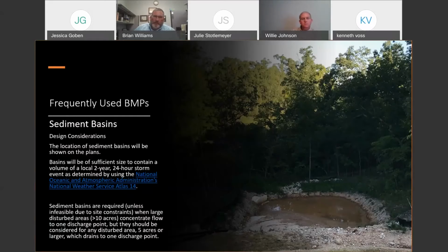Now, I'm going to talk a little bit about the NRCS nomographs that we use in design for hydrology. I'm not an expert in this, but I did a little bit of research because one of the questions that came back when we talked about what everybody wanted to discuss was why we have to use the NOAA Atlas 14 over the nomographs that we have in UPG. What I found out was the nomographs were developed by the U.S. Weather Bureau, Technical Paper 14, in 1961, and they were updated through various other studies in 1973 through 1977.